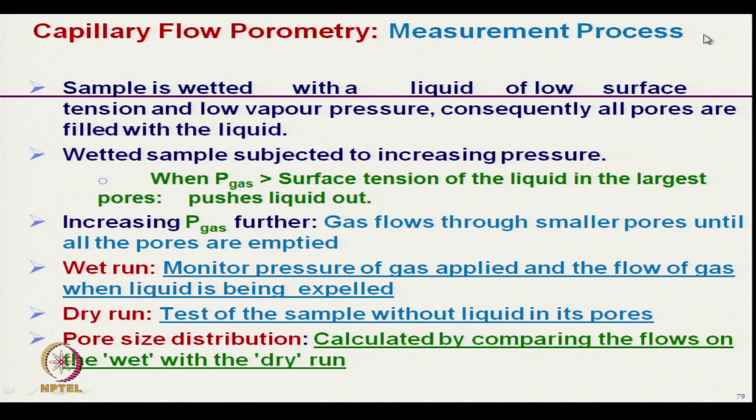The process is that, as I have mentioned here, the sample is first wetted with a liquid of low surface tension, so that it gets wet easily, and consequently all the pores are filled with that liquid. The wetted sample then is subjected to increased pressure of an inert gas.